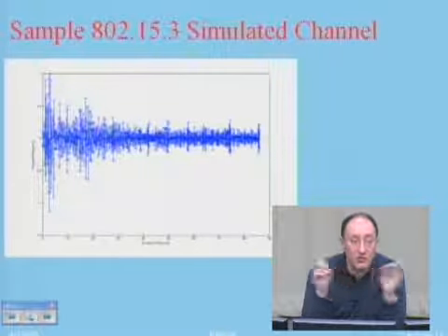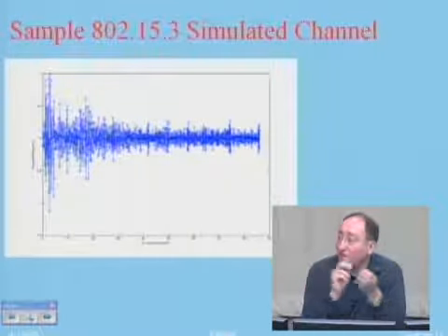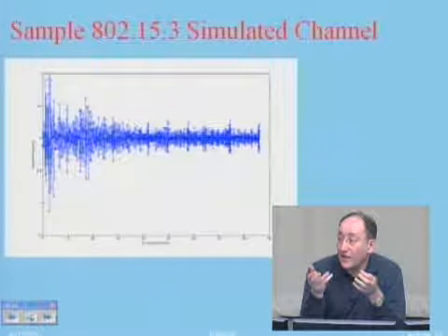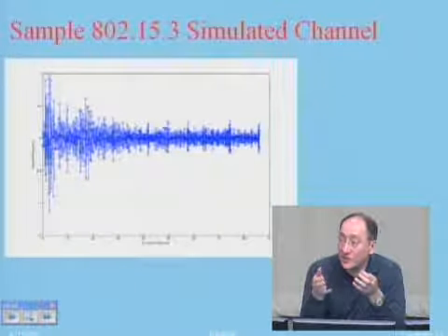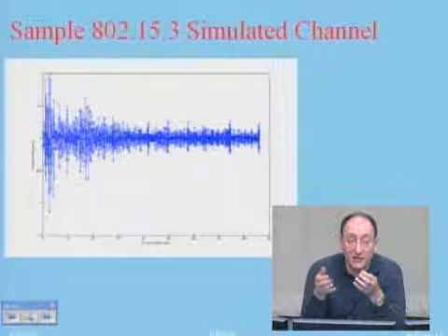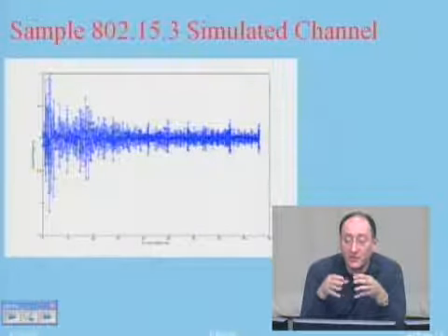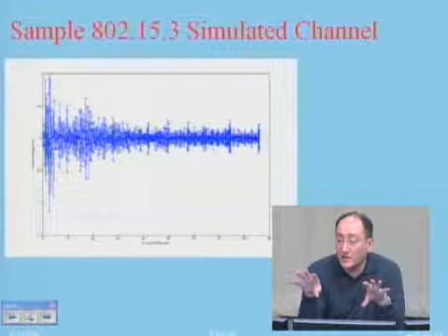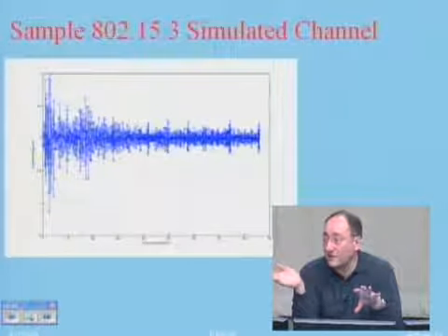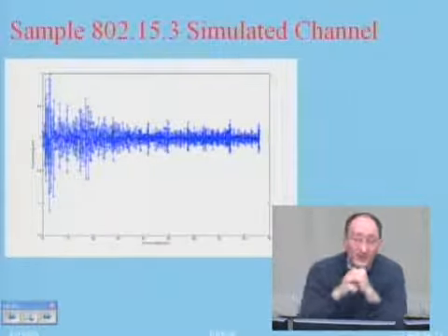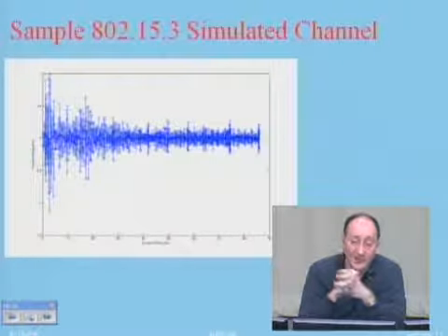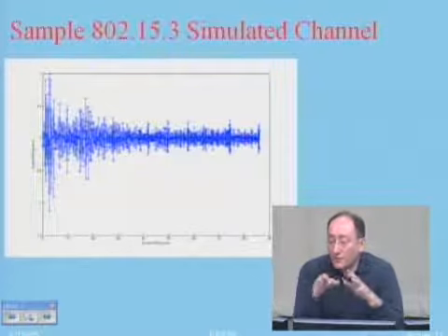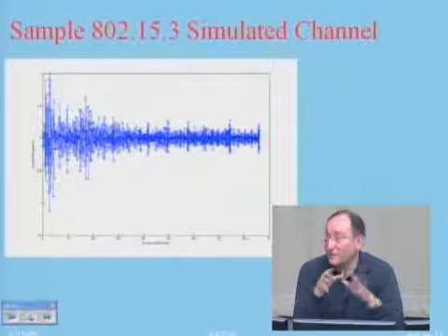Because you have isolated all the paths, the relative phase between them, they assume, is not important. I think it's not a good assumption, actually, in my opinion, because if you take this ultra-wideband model and use it also for other bandwidths, it's not good anymore, or it may be damaged. Okay, but if it is used only for ultra-wideband, it's good.